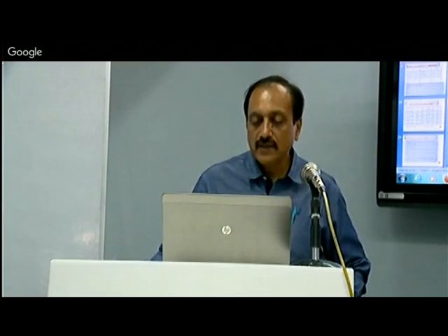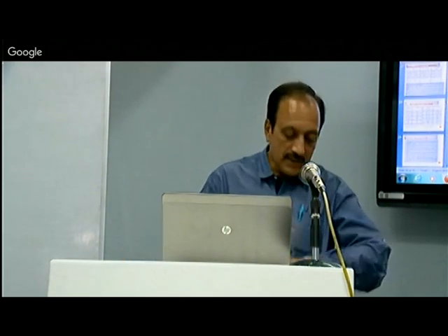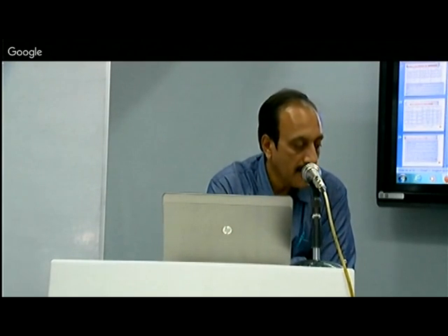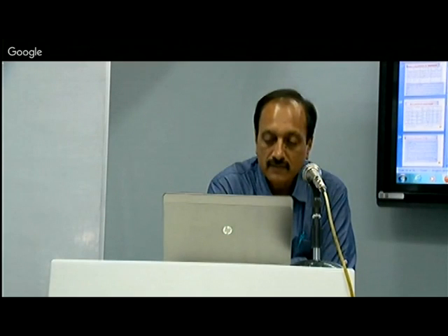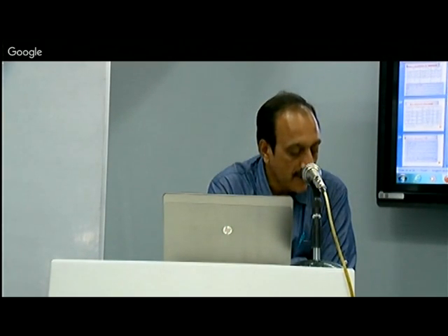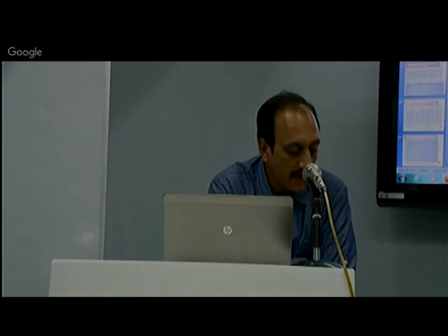So that is how, then बाकी वही compaction using sprinkling, slight sprinkling and finishing is being done. So this is all about the granular layers, granular type subbases and water-bound macadam and wet mix macadam. So in this session we discussed three of them, WBM, WMM and GSB.